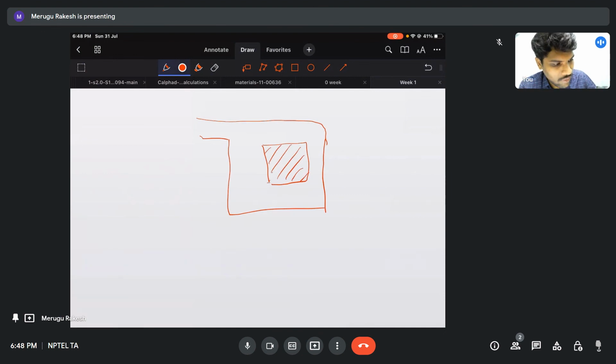Now see, if the liquid metal is coming, initially say it is falling like this, and it is filling, and meanwhile there is also a liquid stream entering like this. If they are simultaneously entering somewhere here, somewhere here, depending upon how pouring is done, the two liquid streams, this is liquid stream 1 and this is liquid stream 2.